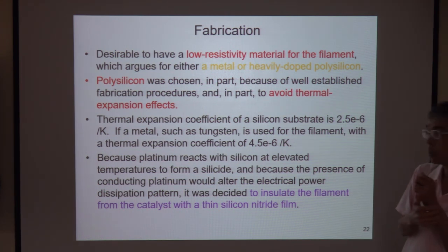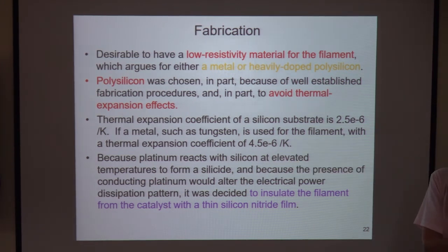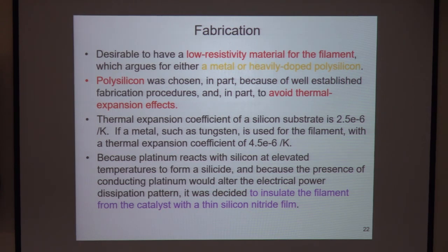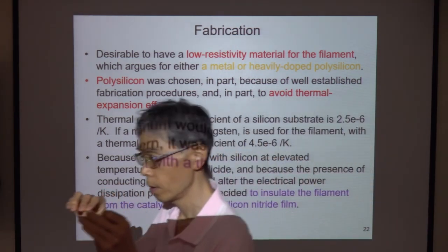Okay, Martin, could you read this? Because platinum reacts with silicon at elevated temperatures to form a silicide, and because the presence of conducting platinum would alter the electrical power dissipation pattern, it was decided to insulate the filament from the catalyst with a thin silicon nitride film.